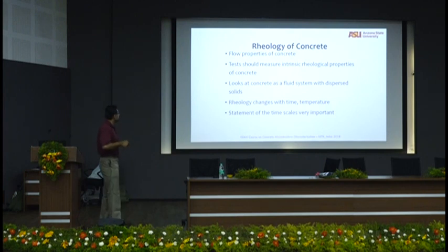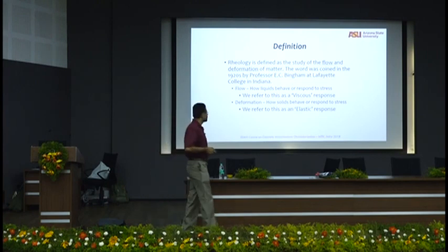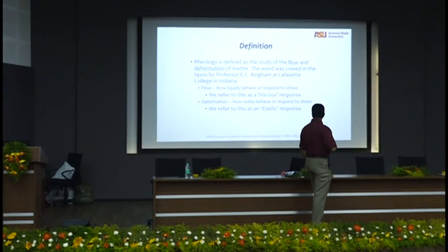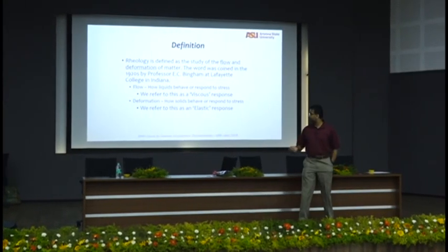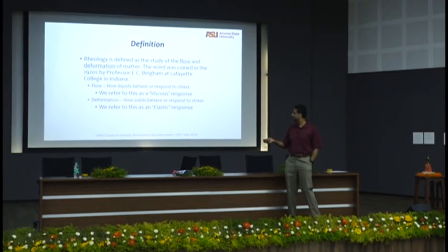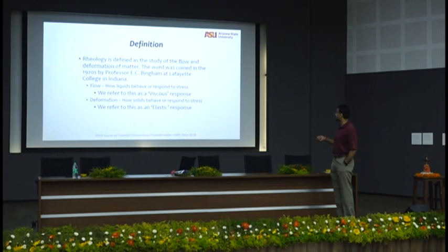So rheology is actually the study of flow, looking at intrinsic flow properties. Rheology doesn't mean just flow alone. Any deformation of matter is rheology. 1920s is when the word was coined by Professor Bingham. All of you know Bingham fluids, Bingham law for rheology, all of that. Okay, so that's the guy. So flow is how liquids behave or respond to stress. Deformation is how solids respond or behave to stress.